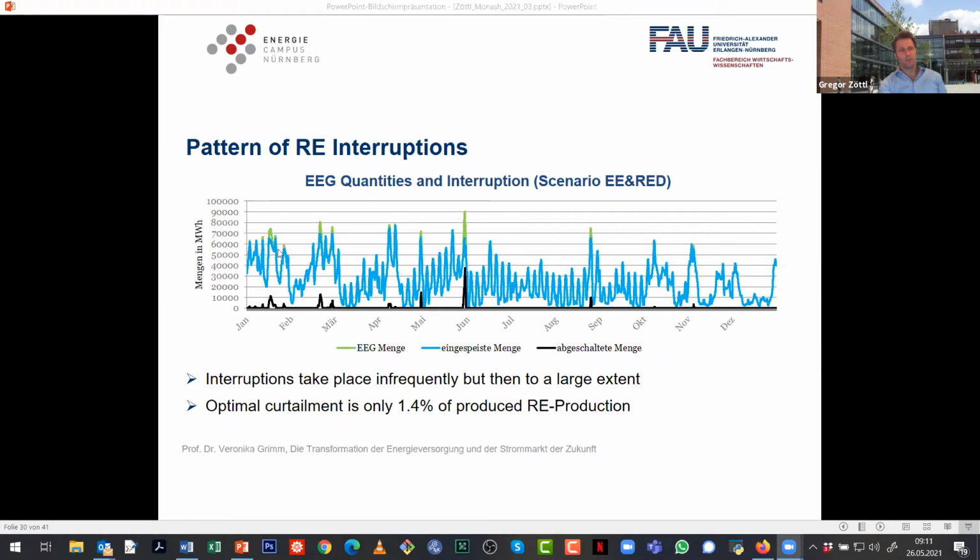And it's unclear what to do with this electricity. If you look at the specific profile, it's not that you can just produce hydrogen within those few hours. It would be super expensive to build an electrolyzer to run for, I don't know, 50 hours or even less throughout the year. So this would never be profitable. Very likely you have to just not produce this, and then turn the windmill out of the wind or something. So in total, the total quantity curtailed would be relatively low. This would clearly be something important to see.